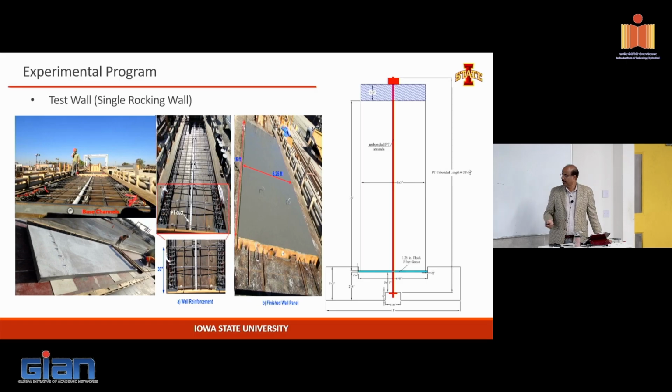So they prefer this pocket so that the wall can be put in place. They can shim it on all four sides to keep the wall straight. So they like the idea. Structural designer prefer it because the shear, the sliding could be eliminated by doing this. There's no way the wall is going to walk away.